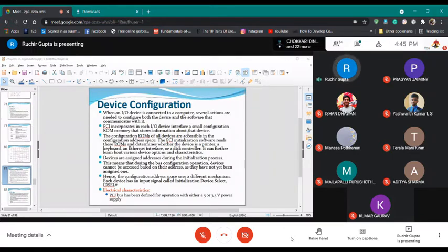The motherboard in which device connectors are plugged has IDSEL pins, that is, selection ID pins, and these are connected to one of the upper 21 address lines, AD11 to AD31. Hence, when a device is selected for a configuration operation by issuing a configuration command, an address is used depending on which ID select pin has been connected. So 1 to 21, actually 0 to 20, has been assigned to this.